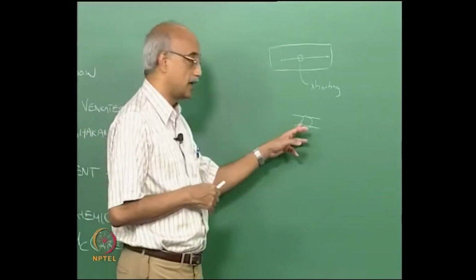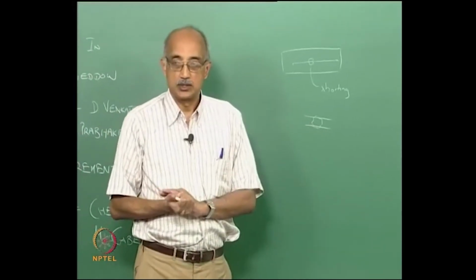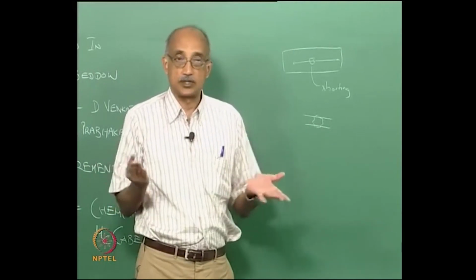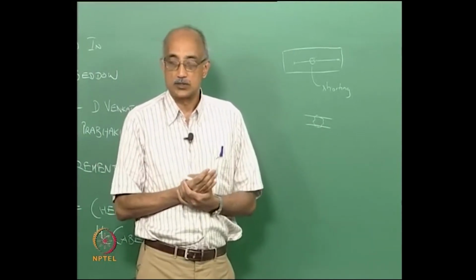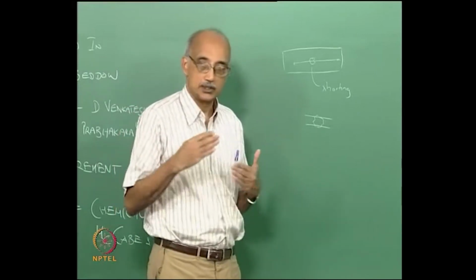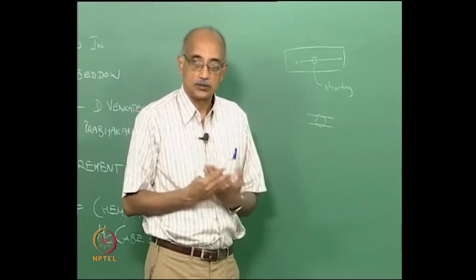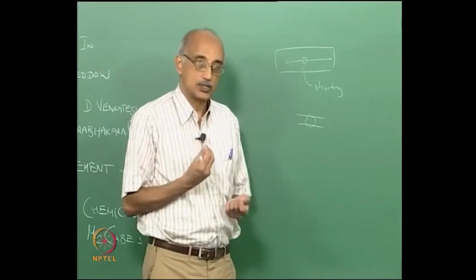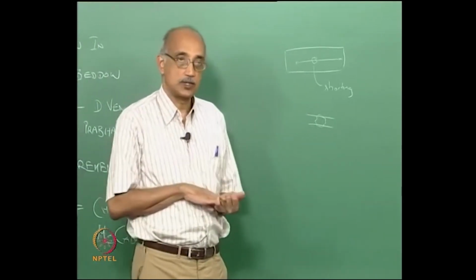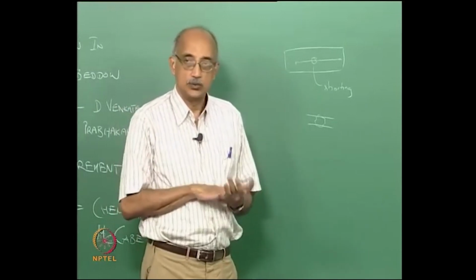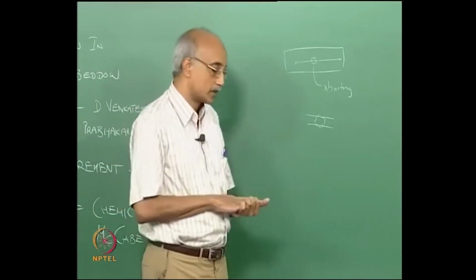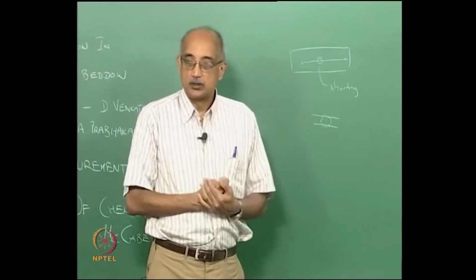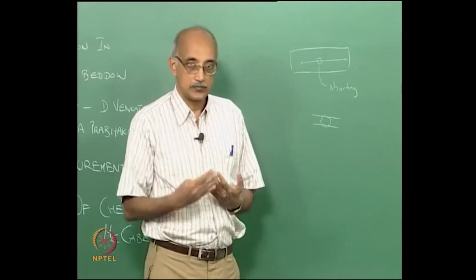However, if this particle has a high adhesion force, then it is going to stay there virtually forever. So, the device is never going to function in the field. So, it is not a short term problem, it becomes a long term problem. So, in this particular illustration, the adhesion forces of the particle that bind it to the surface play a huge role in determining whether it is a simple early life problem or whether it is a long term reliability problem.